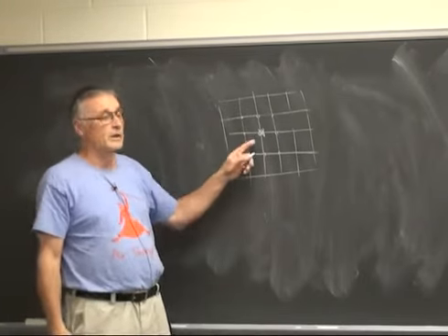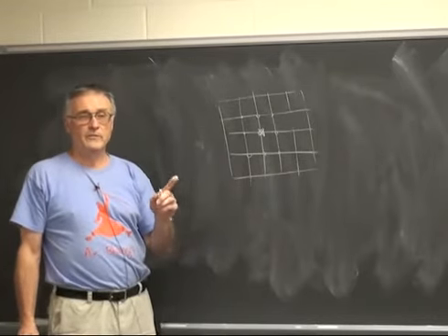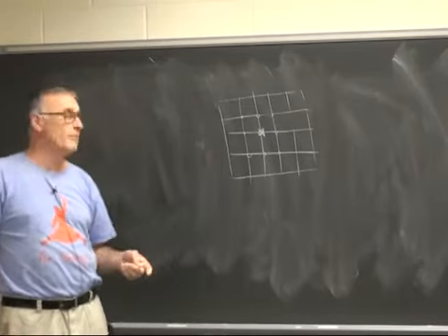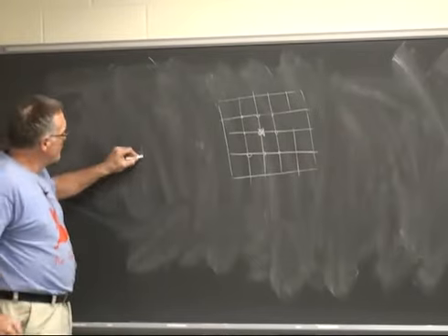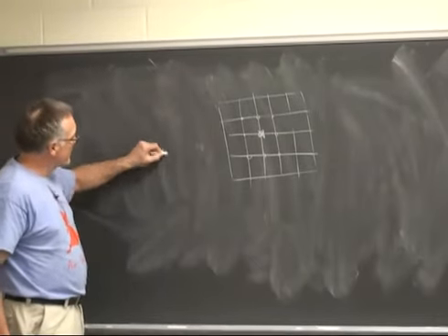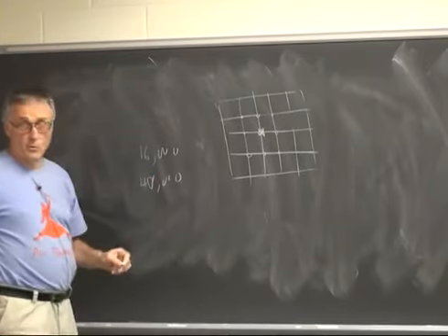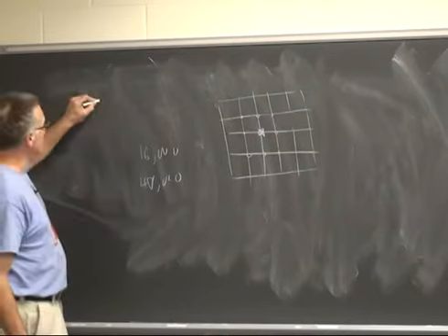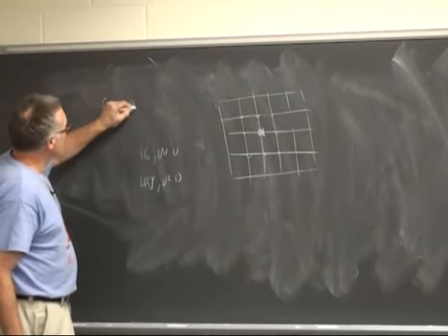So it has to be calculated at real-time rate. It has to be calculated at 48,000 samples per second, or some multiple or some submultiple of that. I don't care whether you compute it at 16,000 times a second or 48,000 times a second or whatever you want, but you are going to be partly graded on the product of the sample rate times the number of nodes.